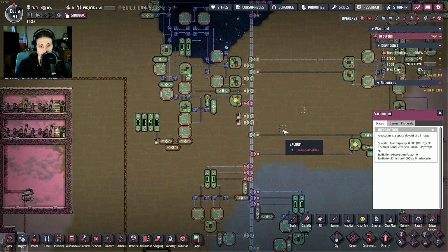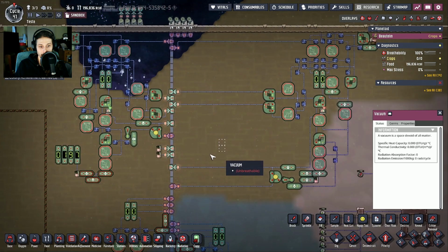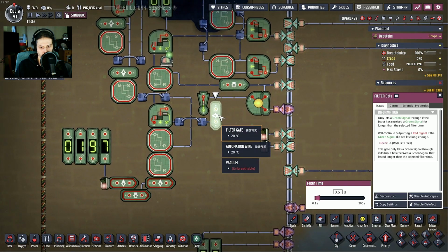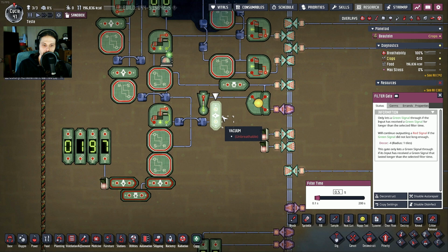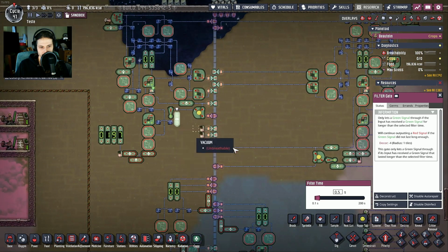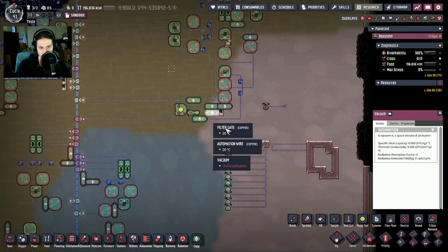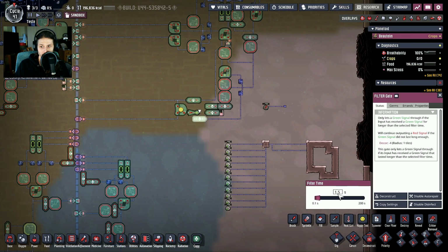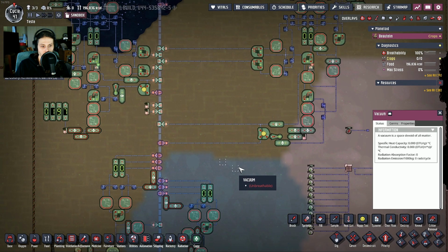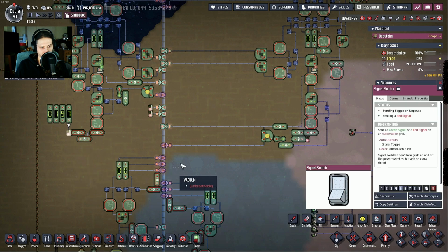Now, it is very important, the bit 3, and everything in this side and in this side is precisely the same, except one thing. This filler gate, this is what we are going to call the priority setup, the setter or whatever. This is the priority thingy. In here, you are going to establish the priority of your system. This is a high priority system at 0.5 seconds. This one is a medium priority system at 1.5 seconds. So, what is going to happen whenever I activate...